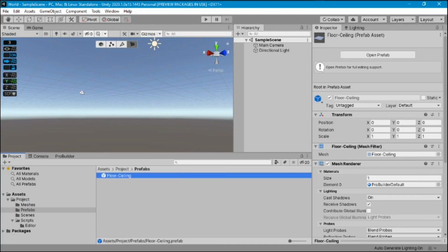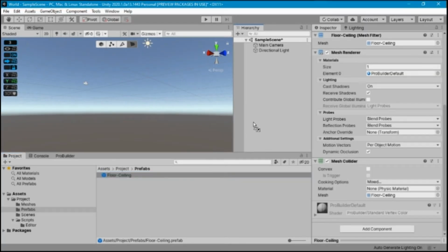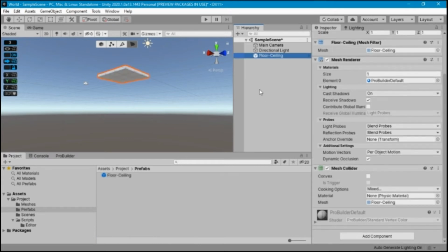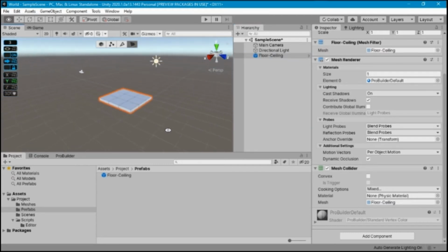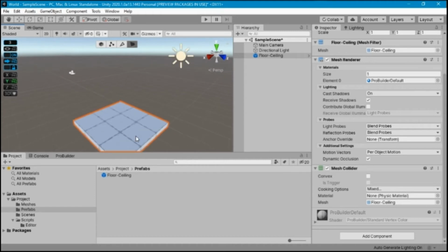To start our test, we need to drag the tile to the hierarchy window. We're going to be moving objects around the scene, and as we do, we may often need to adjust the view to find a more comfortable perspective. Please remember to hold the Alt key while dragging the mouse to orbit the camera around the focused object. Holding Ctrl plus Alt while dragging the mouse allows you to scroll, and the mouse wheel serves to zoom in or out.